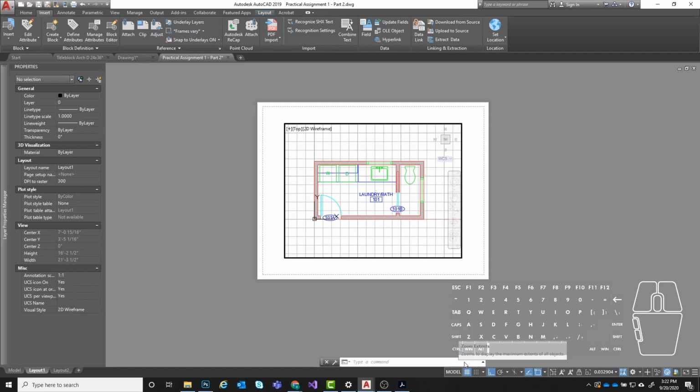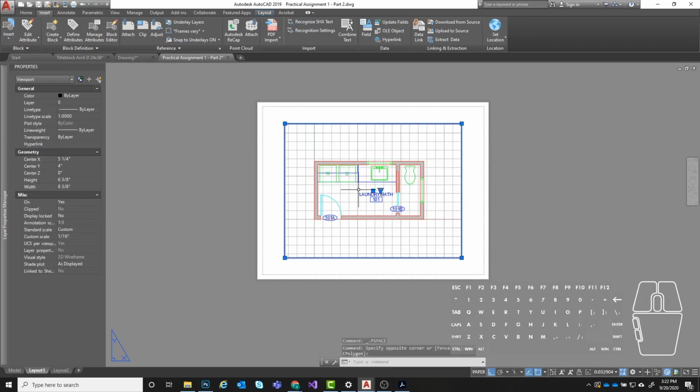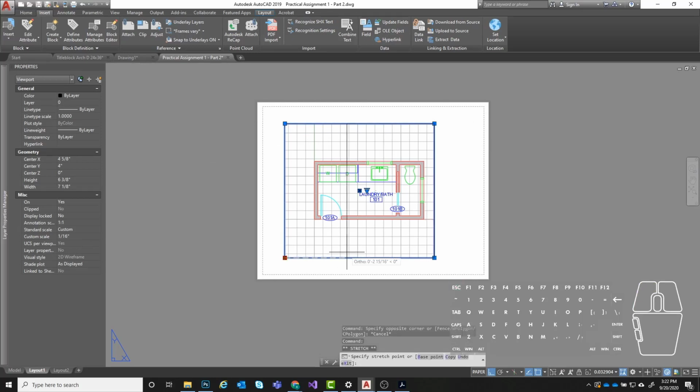And now what I'm going to do is toggle back to my paper space. Okay, so when I have this set up how I want it, you click back on your paper space, and that takes you to being just back on your sheet of paper where you just have these layouts, or these viewports. So once you have something set up on your viewport, you can basically highlight the viewport and then use these blue grips to adjust the cropping, for example. So say I want to crop something out, you can use that to basically control the cropping of what is being shown.